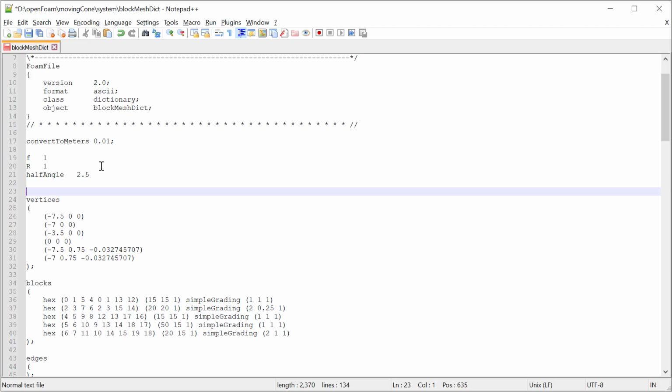And so I'm going to do some calculations here. And when I do calculations, I'm going to call this ZP, z in the positive direction, and we'll call out the calculator #CALC, and then we put the equation in quotation marks followed by a semicolon.